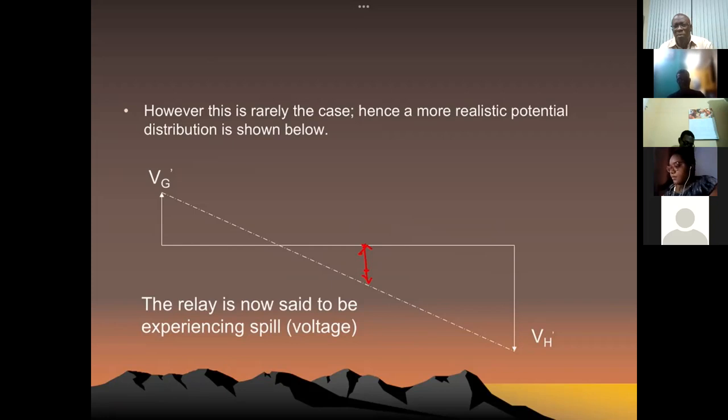Because we're dealing with an electromagnetic device. Yeah. So just by virtue of the CTs, you're going to end up having a threshold current for your relay. So there is an operating current for your relay. It's not that it operates once it is non-zero. There will be a minimum current that will cause it to operate. Right?